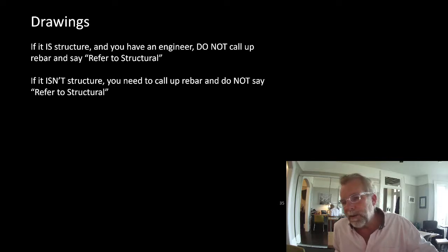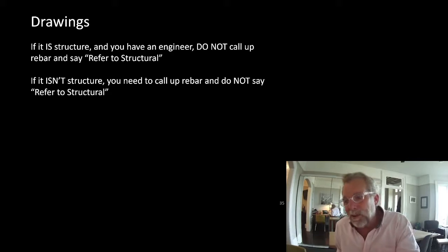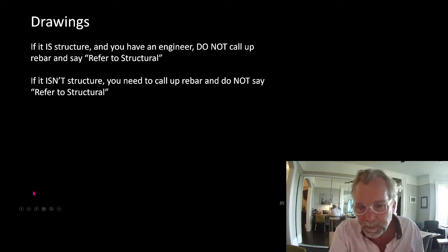So either way, if it is structure or if it isn't structure, the peeve, the takeaway is do not say refer to structural on your landscape drawings. If it is on the structural drawings, it's on the structural drawings. And if it is not on the structural drawings, then you'd better not refer to structural.